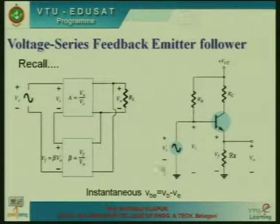Vs is the source, it generates an input voltage Vi between the base and emitter terminals, and the output is taken across the resistance Re here. So, that is Re, the output voltage. The important point we can note here is that this Re acts as a feedback resistor. It is common to the input loop as well as the output loop. So, it is a feedback element here.